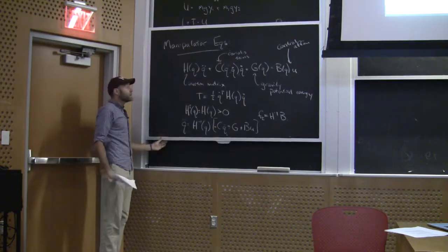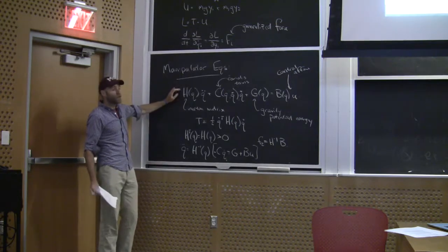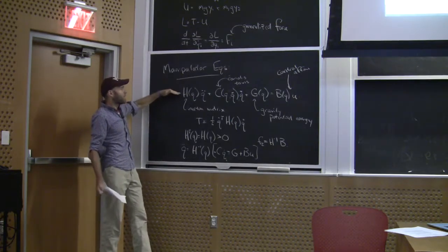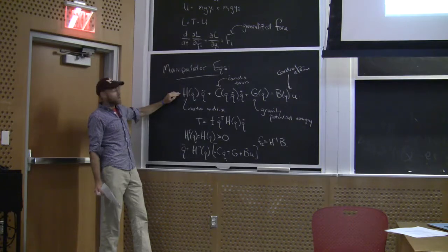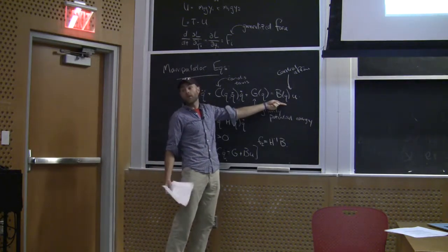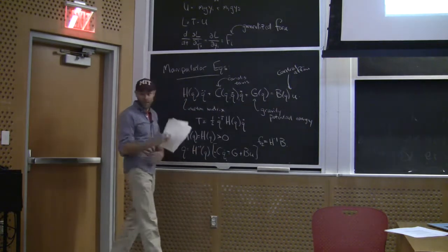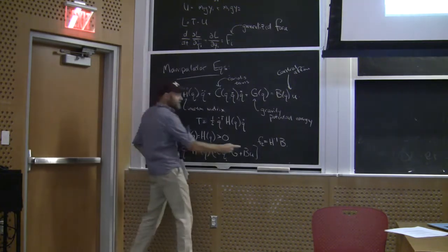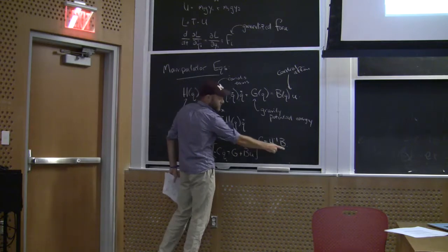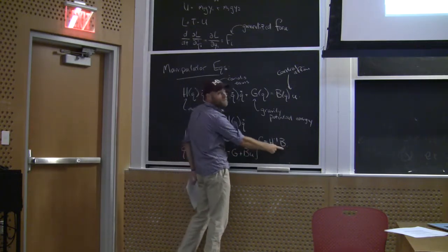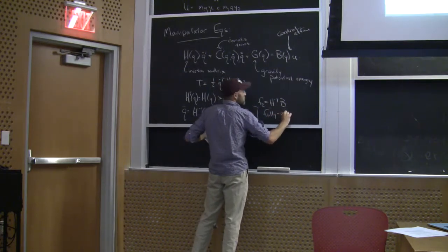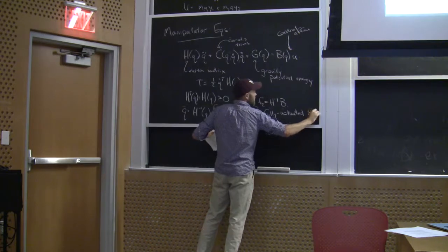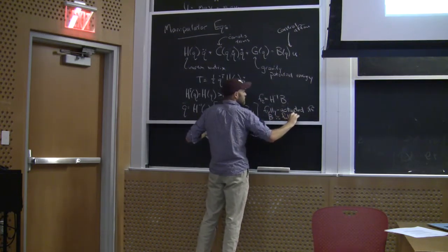Okay, so let's say you have a robot, and you've called your software, you've done your derivation, and you've got this equation. What's going to tell me if it's underactuated or not? What's the easiest check? B has to be full rank. It could be square but have zeros in it or something, right? Since H is always invertible, the requirement for F2 to have full row rank is that B be full row rank. Fully actuated if B is full row rank.